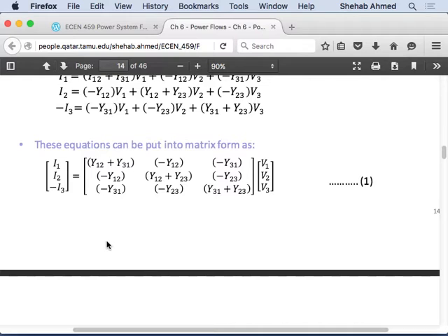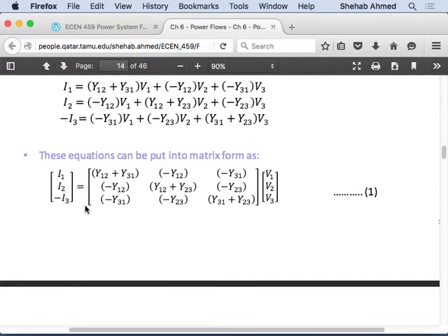If I have V and I solve for I, I take I equals the admittance matrix times V. Then I have P and Q on one side, and on the right-hand side I have a bunch of voltages and admittances, and these voltages have magnitudes and angles, right? And I have a bunch of P's and Q's on the left-hand side.